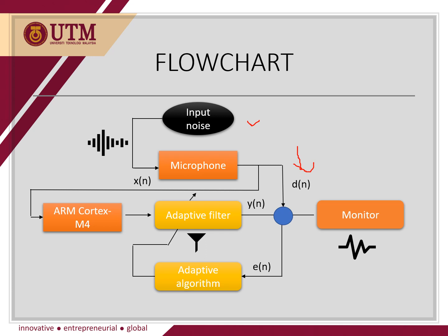After that, the car will be moving and the input signal will be captured through a microphone connected to the ARM Cortex-M4 board. Then this input noise will be filtered using an adaptive filter and analyzed using the STM32 platform with the help of the CMSIS DSP library, which contains the adaptive algorithm, which is the LMS algorithm.